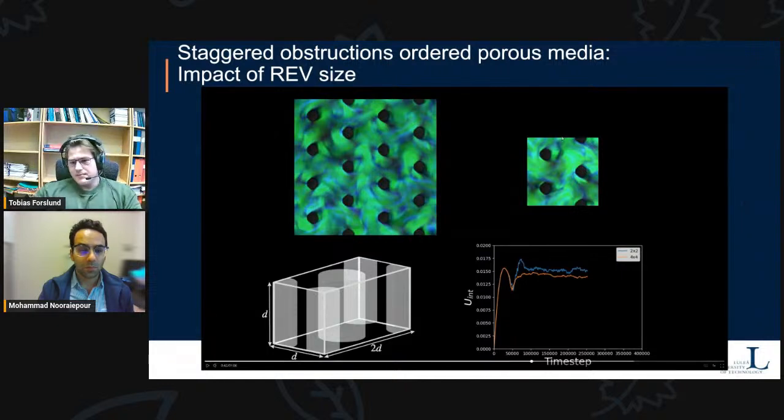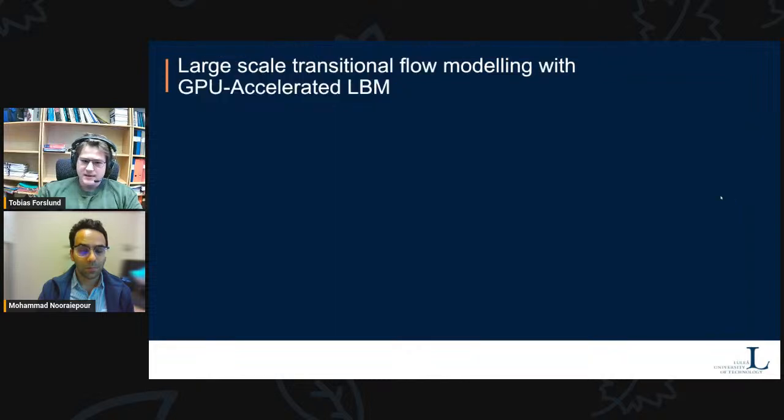I've seen some cases where people would be happy with just using a representative elementary volume like this, but usually if you're doing temporal simulations, you should really investigate how large it needs to be.